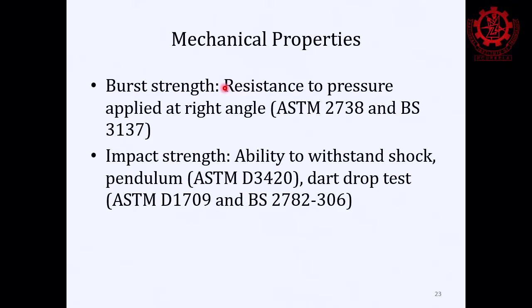And impact, which is different from burst, is where you apply sudden pressure or shock. For example, if you take a glass and put a probe on it and start applying pressure, it will break only after a very high amount of pressure or force. But if you have an impact, which is a sudden force, then with a very small force it will break.